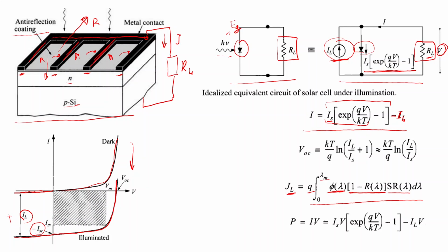And this is spectral response or quantum efficiency. So it tells how many photogenerated charge carriers will be created per 1 photon which was absorbed by the semiconductor material. So it's kind of internal quantum efficiency. We will discuss this parameter a bit more.